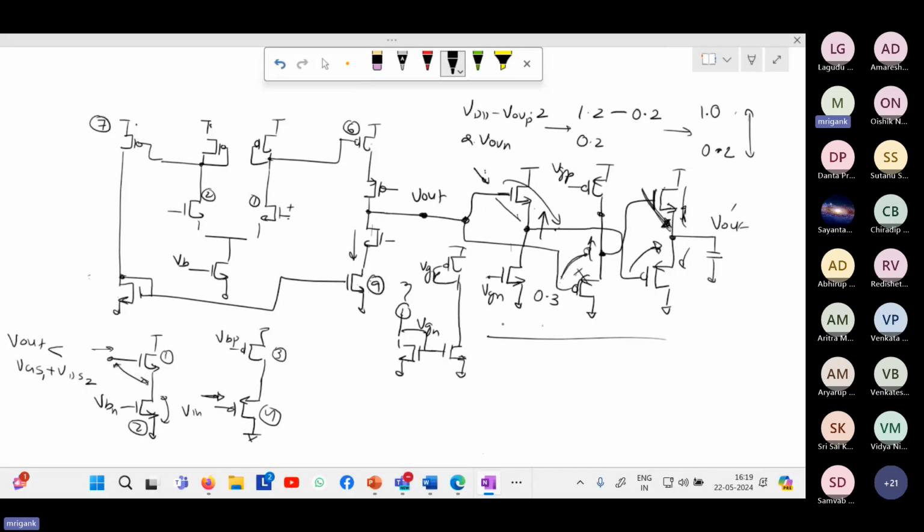in the case of voltages where both are on, say the NMOS is on and the PMOS is on, when both the stages are working, you get overall AC signal coming from this one also, from this one also. As a result, both of them work as common drains. In that case, you can take a superposition, and effectively the output will still give you the voltage follower operation. For the extreme cases, one of them will be off. For very high voltages at the output, the PMOS will be off. For very low voltages at the output, the NMOS branch will be off. And at intermediate voltages, both branches will be on. Is that clear?